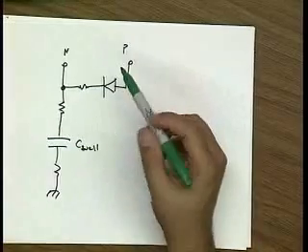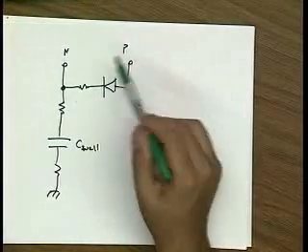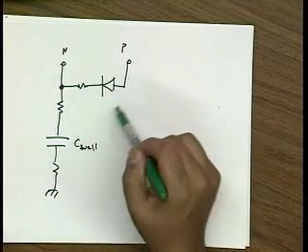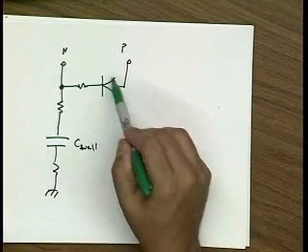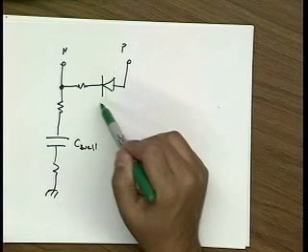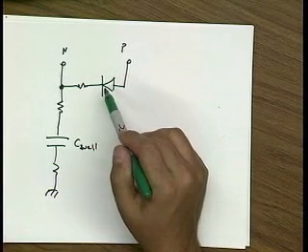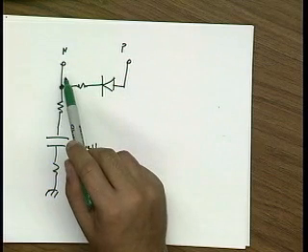So if I'm going to use this diode in my oscillator, what I really want is the capability of changing the reverse bias voltage to change the capacitance, and I really would like to avoid putting this node on my tank, right?